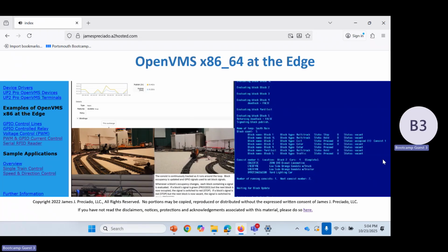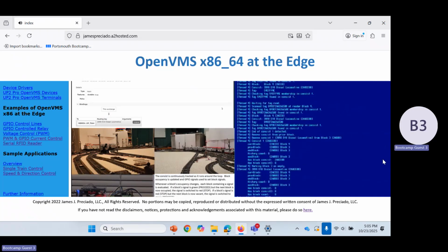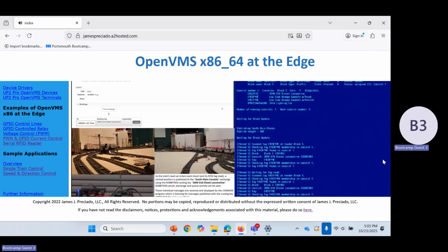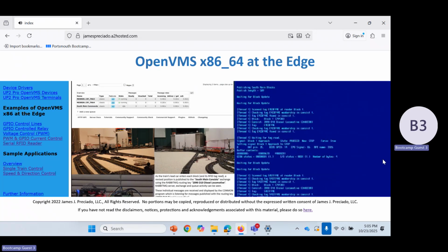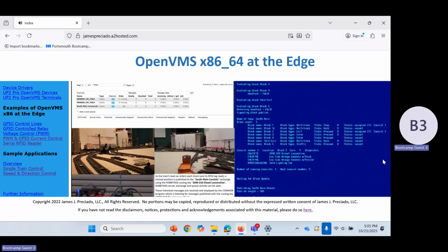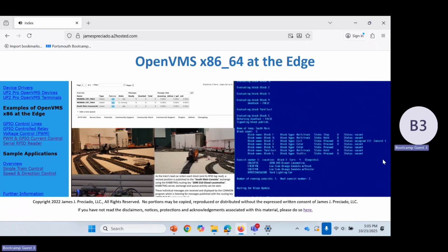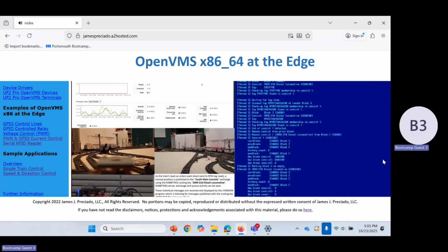It actually built the list of the train cars that it's tracking based on the RFID reader. You go back to the beginning and look at this, the first time it picks up an RFID tag, it says it's a new set of trains that I haven't seen before. I'm going to start building it and keeping track of where it is. It uses a small in-memory database to do this. Certain cars have a property, like searchlight car, that says it's an end car. So when I read that, I say, okay, this group of cars is complete. If there's another one behind it, I'll find it or not.